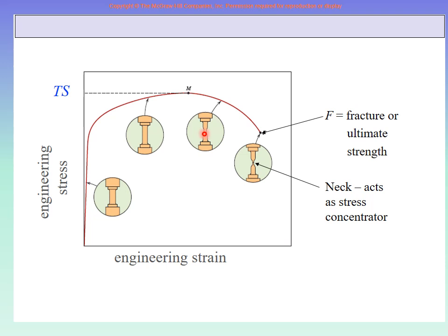Now you know that necking means that here there is a smaller diameter. So when it is here, anywhere here, you have a certain force that you have applied. You divide that force by this diameter, then there will be some stress. But you divide the same force by the neck diameter, right? The stress will be higher because this value is smaller. So at the neck, the stress is much higher compared to the rest of the specimen. Therefore, ultimately it will break from here.